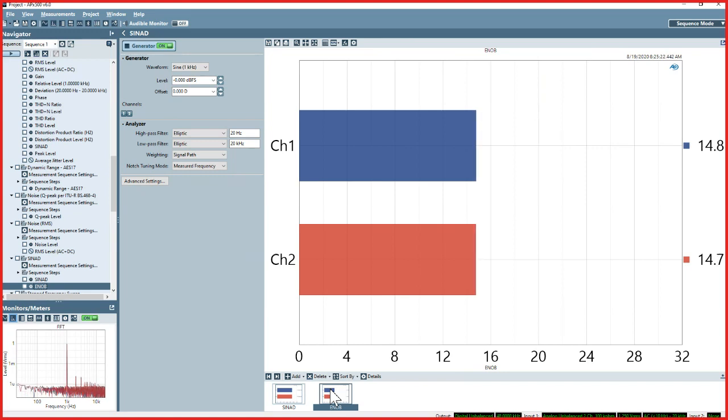And so, again, there's a little bit more detail into it, but the basic thing is we can take the SINAD or the THD plus N and divide it by 6.02 dB, and that tells us how many useful bits we're actually getting. So in this case, you can see that in this converter, we're actually pretty close to its theoretical 16-bit performance. We're getting 14.7, 14.8 effective bits.